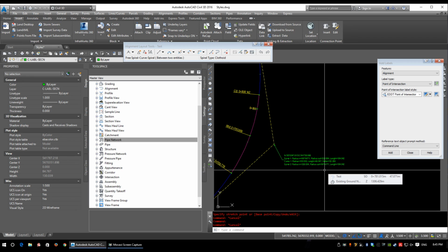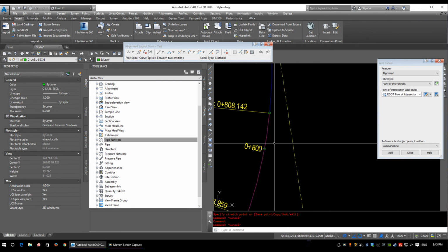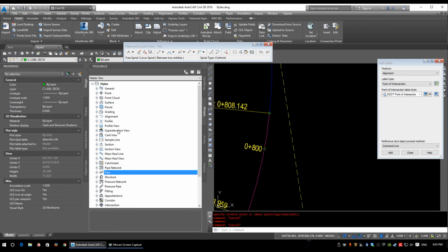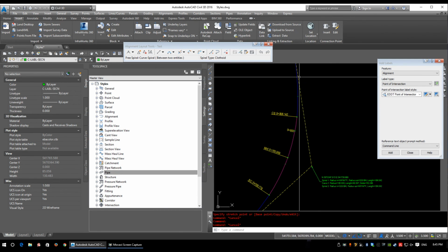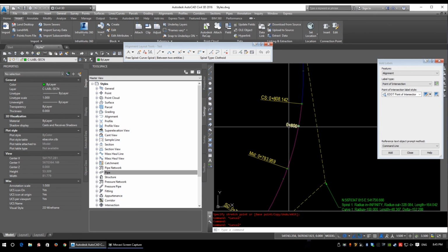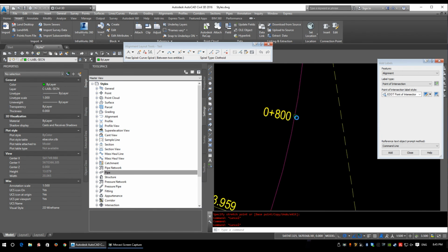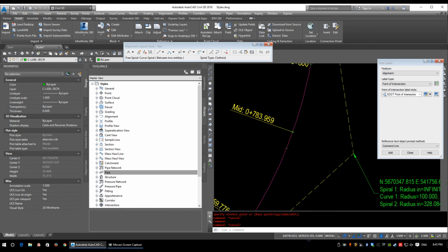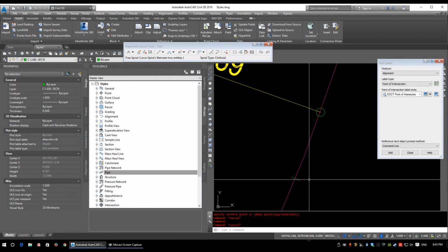So as we've seen three videos now on label styles, they are a very large part of Civil 3D, and having everything set up properly is a ginormous task. There's thousands of label styles, and if you have multiples of them, it can easily turn into 2,000-3,000 label styles showing different pieces of information. So name things descriptively and keep everything consistent. If you use the little circle, always use the little circle. If you use the tick, always use the tick.